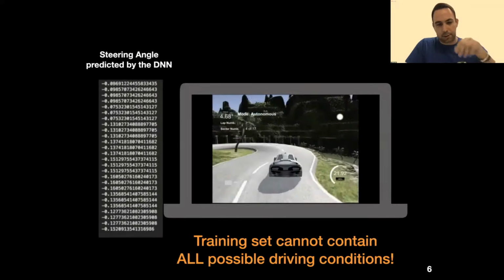The main objective of this research is to try to predict whether a car is facing an unsupported scenario before the actual misbehaviors are observed. And our main approach revolves around monitoring the unexpectedness of the driving scenario. Suppose this self-driving car was trained only on sunny driving conditions. As such, we need to devise an unexpectedness metric that is low when the scenario is known, and it is instead high if the conditions are unexpected, for instance, when it is suddenly raining. Our purpose then is to automatically set a threshold to determine when the unexpectedness is rising over an acceptable level.